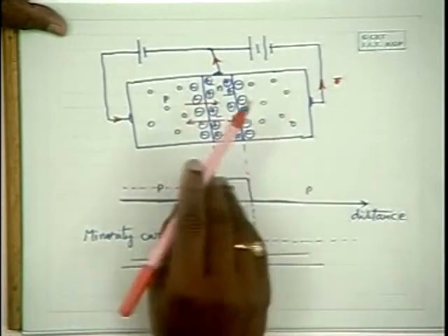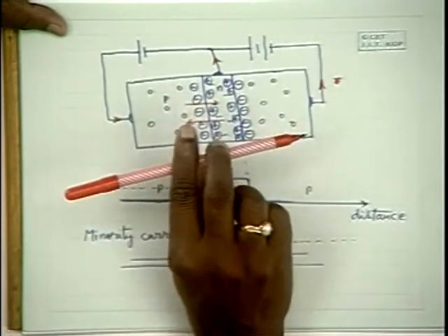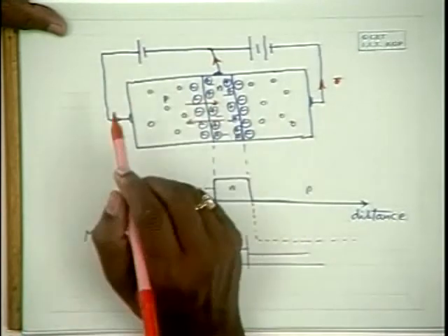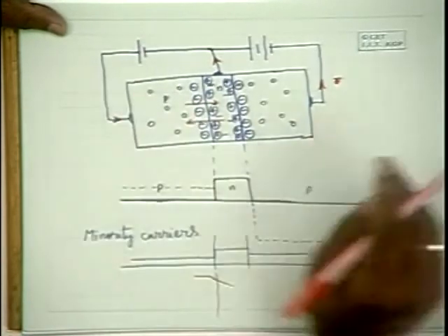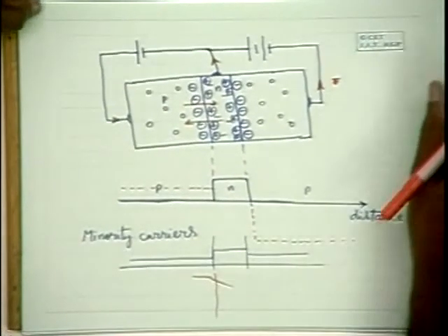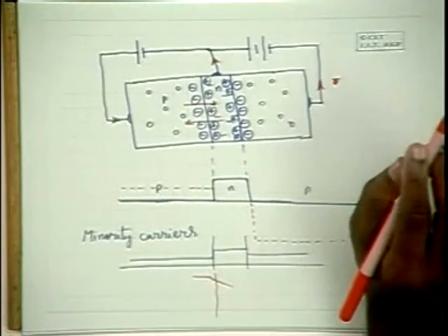And this injection of the holes into the base region, or diffusion of these, naturally depends on this forward potential here, this junction potential between the emitter to base junction. Any questions on this diffusion of the holes from the emitter side into the base, and the drifting of these injected holes into the p side by the reverse potential applied across the base and the collector?